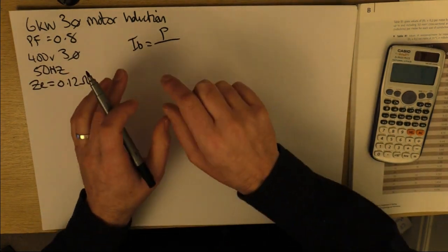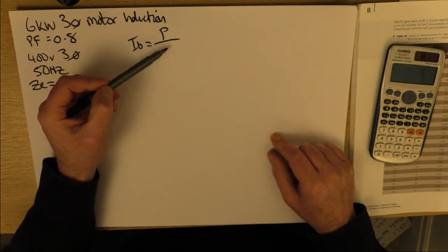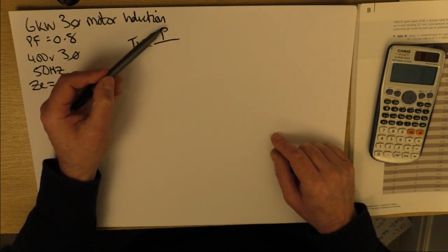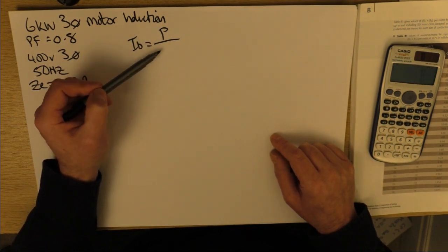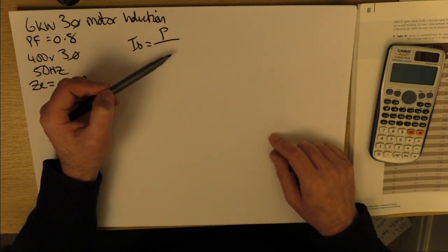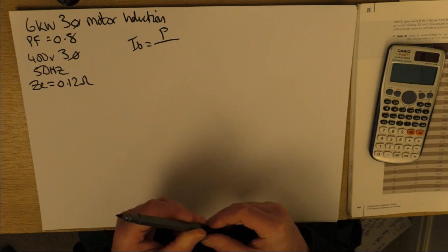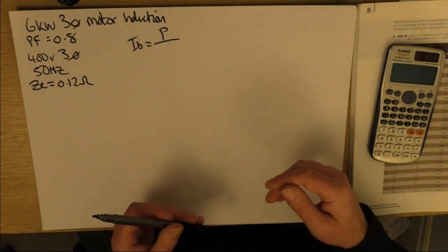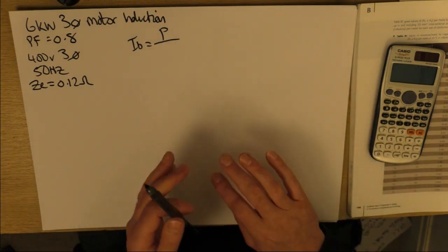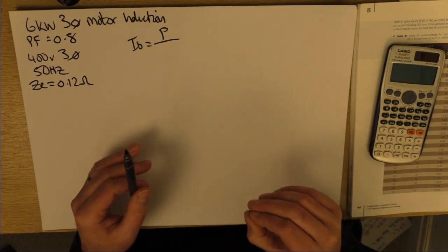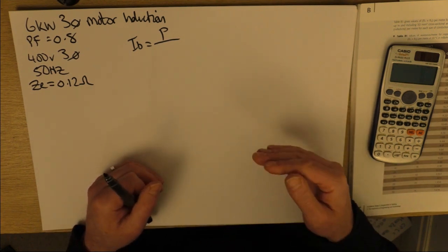But just remember that you can't just put in any voltage here. The manufacturer has got that power by applying a certain voltage. I see people get confused with this all the time, especially showers and stuff. They go, yeah, but if the voltage goes up, then the current comes down. It's just not true. A shower is a resistive load. The resistance hasn't changed. You increase the voltage, the current's going to increase.